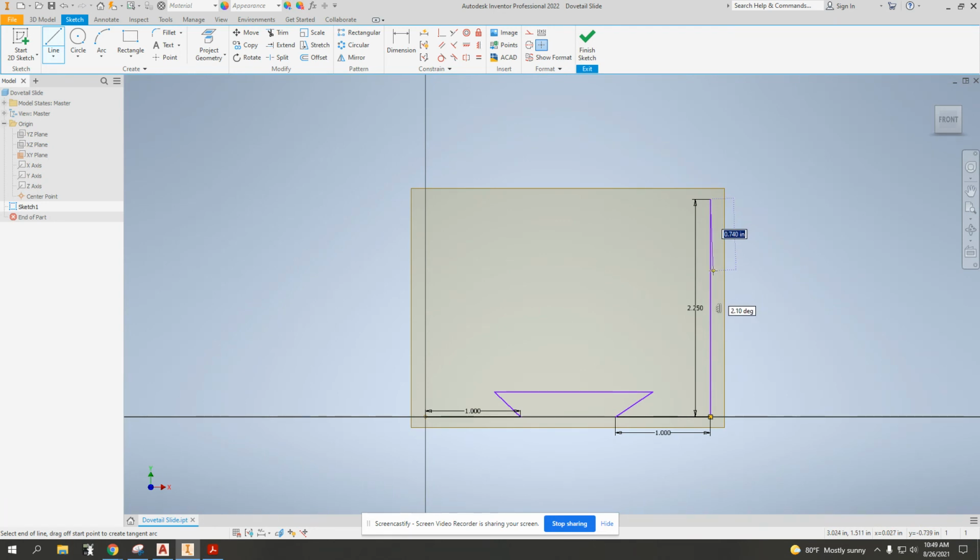It's not currently fully constrained because I don't know how far it is away from our origin point quite yet. I'm now going to go horizontal back over to the vertical Y line and make sure that it is, in this case, I'm seeing a perpendicular constraint icon. It looks like this. It's a perpendicular constraint. It's making it perpendicular to this line, or maybe the X lines down here. I am on that Y vertical 0 axis. So I'm going to left click to place that.